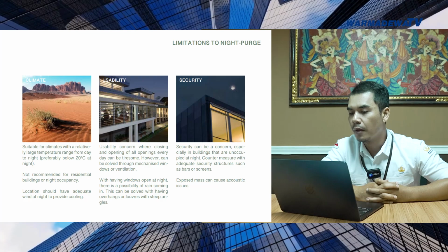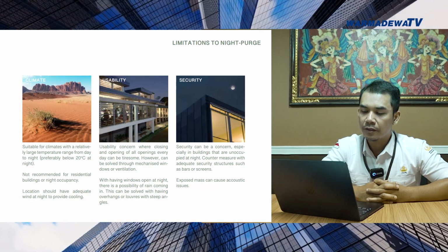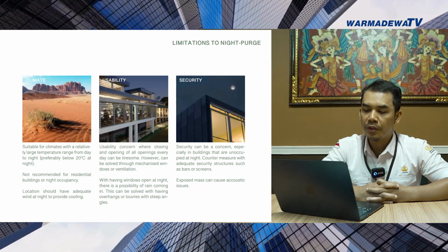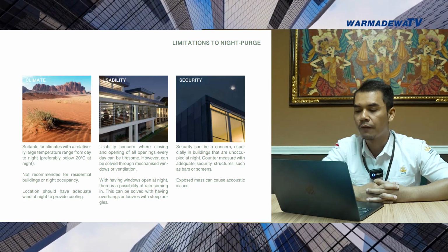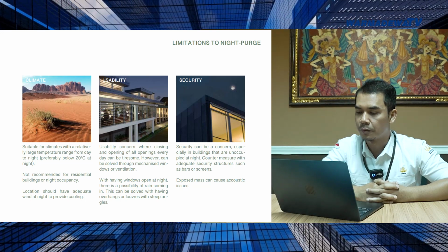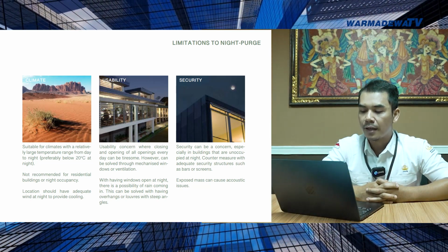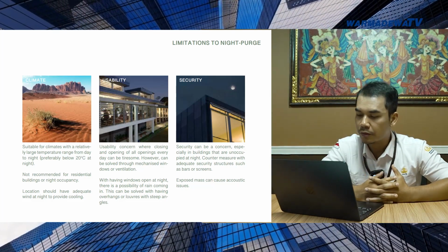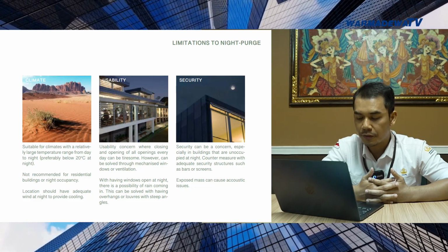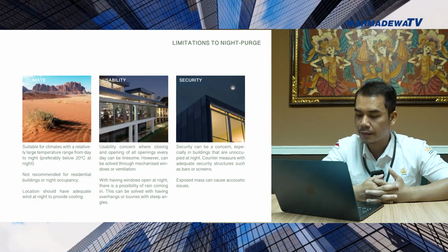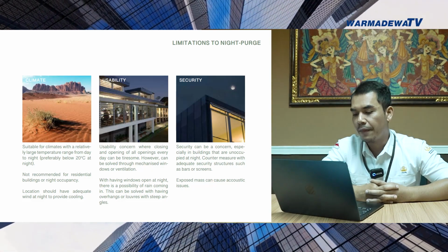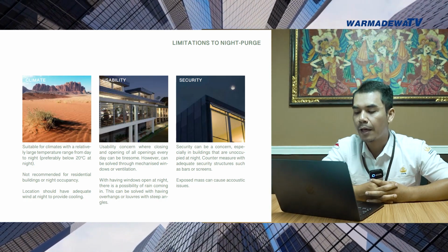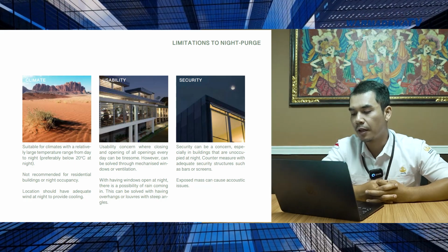During the daytime, heat gained from the outside temperature is absorbed through thermal mass. This means that the building must be made with materials that have good thermal mass absorption rate. Now, during the nighttime, the heat that is contained within the building's walls or floors or any other surfaces that have good thermal mass will be released, and then the cool air during the nighttime will absorb the heat that is released and will flush it out into the outside area.